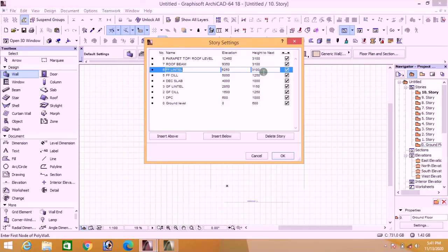Now, on top of these 2 courses of block that we have left, we are going to change the entire structure with a roof beam. That roof beam measures 250, which means 250 plus the 750 that we now have gives us 1000. So we are adding 1000 at this place, right? 1000. That brings us to roof beam top.